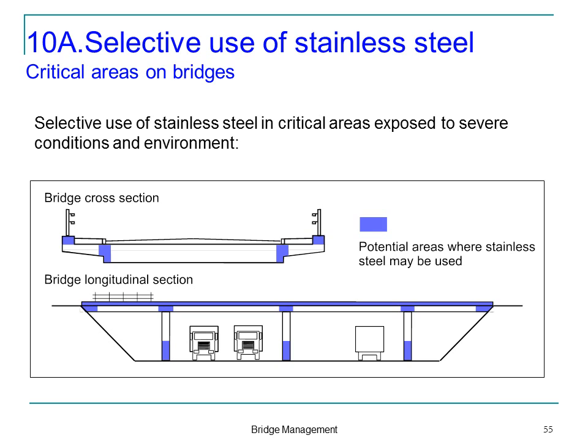I mean, if we have observed it in a couple of thousand or worldwide in 100,000 bridges, then we know, for instance, if we have a road with de-icing and so on, well, then the lower part of the columns will probably have corrosion. The top part of it will not. So we put in stainless steel here, but not there.